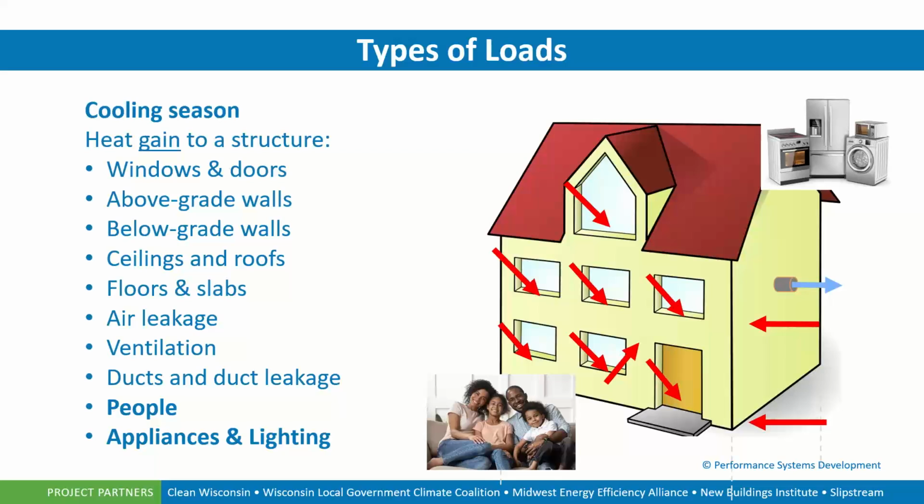So in this situation, the walls are light. The roof could be a medium or a dark, depending upon how we interpret that color. Both of those are going to affect the heat loss and heat gain through the structure itself. So we lose, again, cooling through our ventilation systems, conditioned air to the outside. That's going to be a heat gain because we're extracting that air to the outside. We're bringing air in through any leaks in the home. So unconditioned air during the summer coming in is going to increase our cooling load.